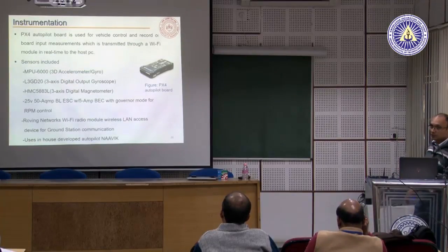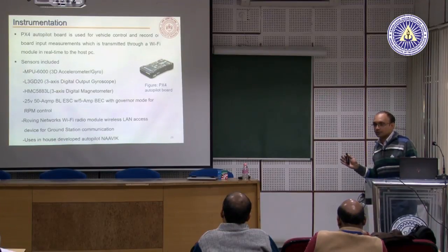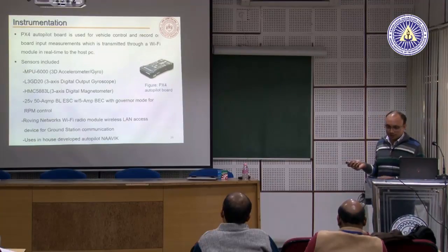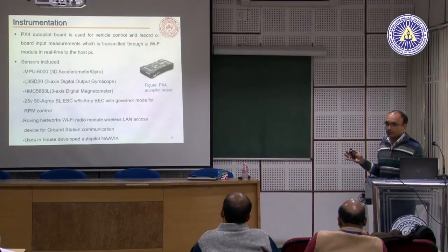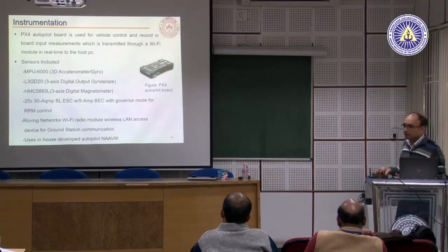The instrumentation which is done: on board we have this PX4 autopilot board. Yesterday one of these boards got reset in the middle of the flight. As a consequence, the pilot just lost complete control and it crashed. Normally this is a very reliable sensor, we have been using it for quite some time, but last time when we had an accident, we were using a Chinese version of this. It was a pirated version of this particular autopilot board. So we thought it was because of that, but yesterday, for the first time, we had a failure with an original Pixhawk board. But it is an old board, so maybe that is the reason it failed.